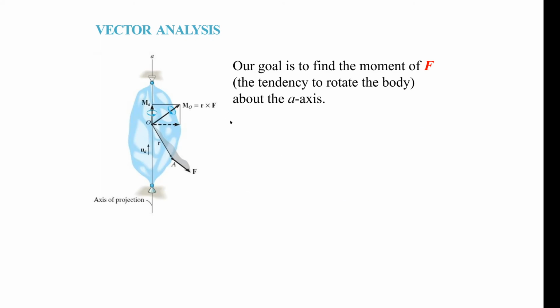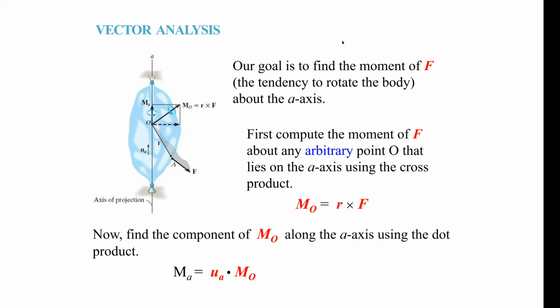And a more general approach is that you can do two parts to this. The first part is finding the moment about a point, some point. In this case, we're looking for the moment about A. Okay, this is A. This is the line of action A. It could be an axis, but this is just some line of action A. And what we want to find out is how much of the initial torque we have is used to turn about this line of action. Okay, about A. How much of the moment is about A, which would cause rotation about A.